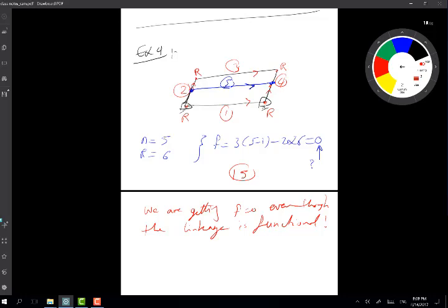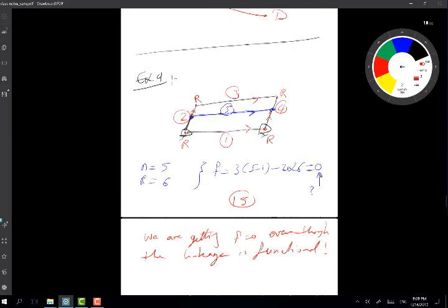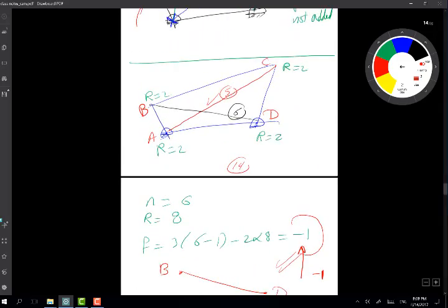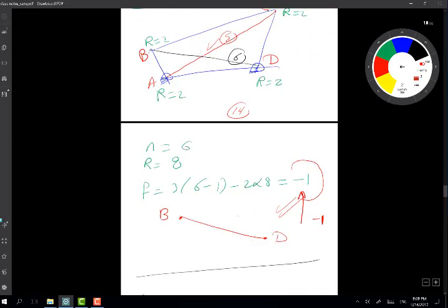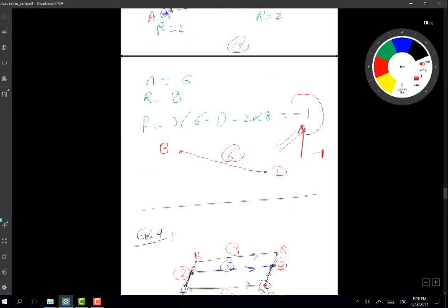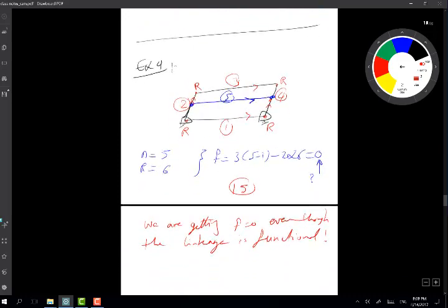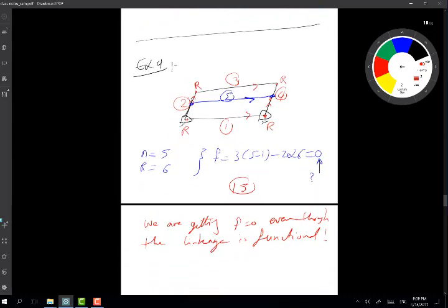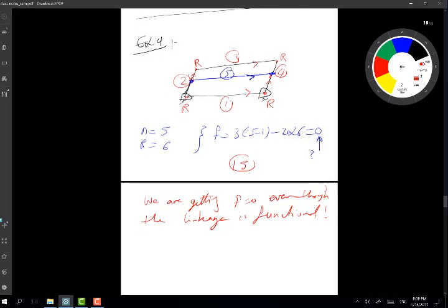This rings a bell for us, and it tells us there is a geometric constraint, right? Exactly like we had previously, where link number 6 had to be manufactured to a high level of accuracy. The geometric constraint here is that link number 5 has to be exactly parallel and equal to 1 and 3, and with any deviation from that, this linkage is not going to function.